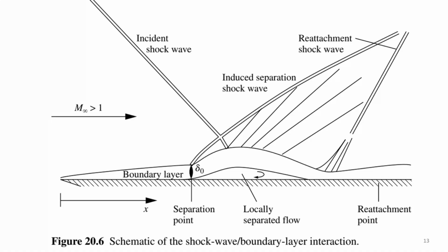Another classical solution for viscous flow and for Navier-Stokes equations is this shock boundary layer interaction. It can be performed in various forms. It can be performed in this simple form with the flat plate and reflected oblique shock waves. It also can be performed as an interaction of a normal shock wave and boundary layer, or interaction of a shock wave with some angle of attack or some inclination of the body.